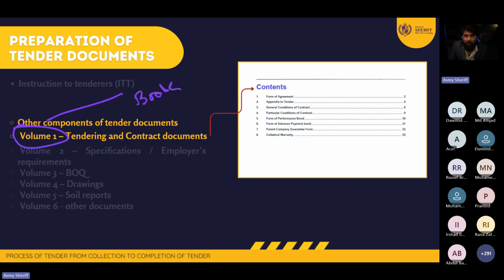In that, what are you going to put? You're going to put what our general conditions of contract are. We are following the FIDIC Red Book, for example. So you need to tell about FIDIC. We are following FIDIC 1999. Normally we don't put a copy of the document; or on a paper, you need to mention our general conditions of contract, FIDIC 1999 Red Book. And not only that, you also need to tell him what changes I need to make to the general conditions.